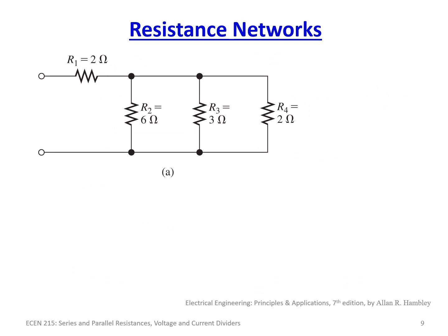So now we have another circuit here. Here we have, again, 4 resistors. This time we have a 2 ohm that is in series with our 2, 3, and 4 that are all in parallel. So what do you think we should do first? Let's look at this. Well, I would probably start simply by solving for this part. So let's do that.